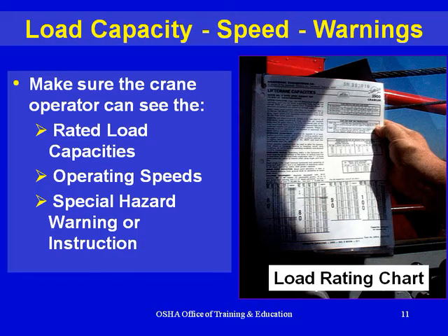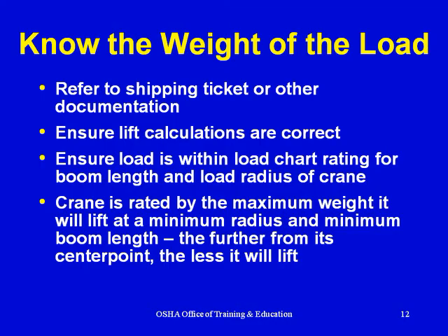Load capacity, speed, warnings. Make sure the crane operator can see the rated load capacities, operating speeds, special hazard warning, or instruction. Know the weight of the load. Refer to shipping ticket or other documentation.